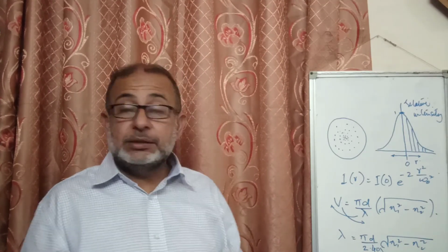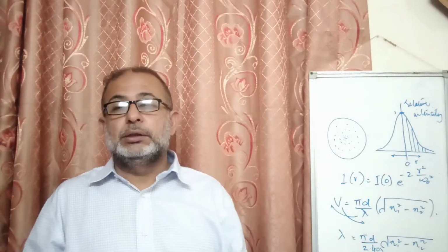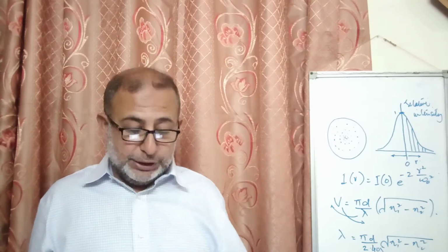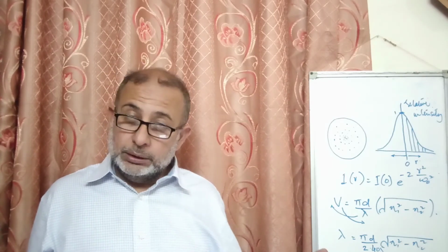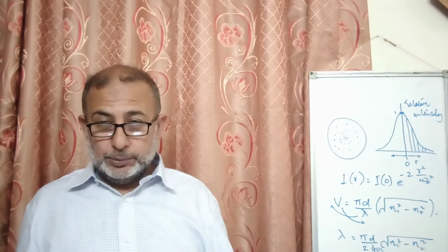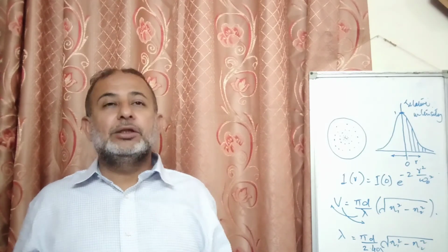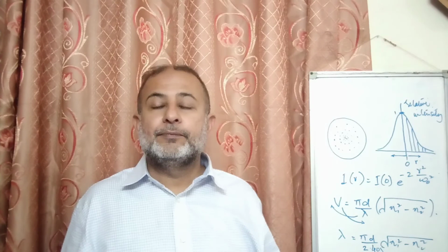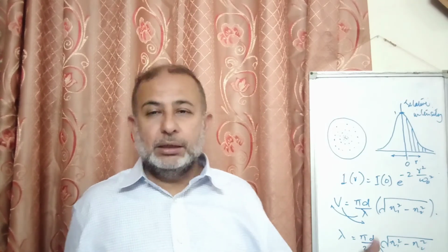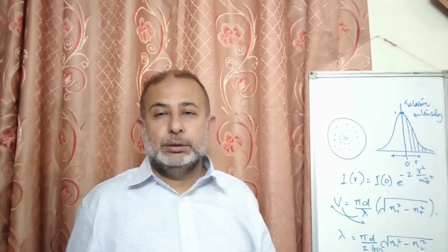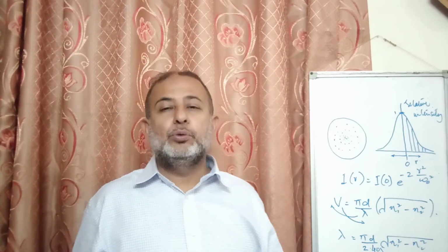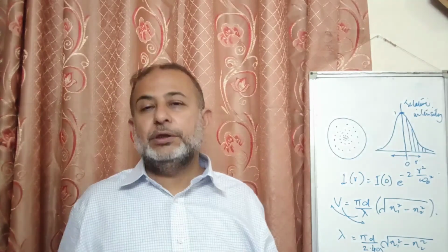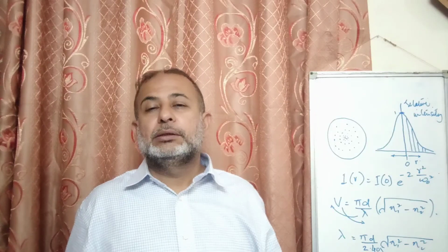Actually, in a single mode fiber, attenuation is more of a problem, while in a multi-mode fiber, dispersion is much more of a problem. The reason is that modal dispersion is not present in the single mode fiber, while there are other types of dispersion in single mode fiber that we do face. And the most profound of it is the chromatic dispersion.